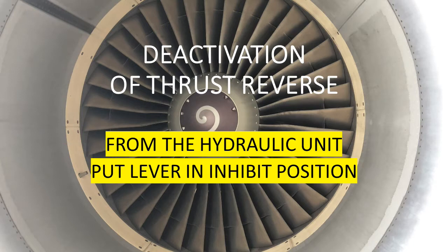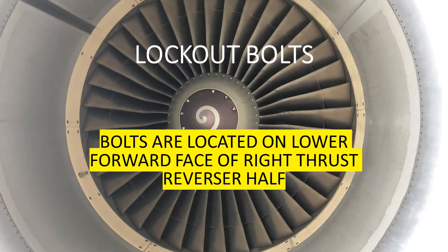Okay. All right, and that's on the hydraulic control unit. There's also the lockout bolts, which are also used for deactivation and lockout. They are located on one of the doors. They have a little bracket where you can remove them from that bracket. All right, and again, this is locking out the pivoting doors. And there are places where you would put those bolts to lock that out.